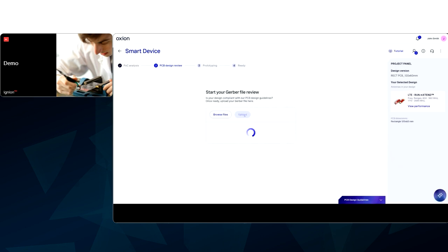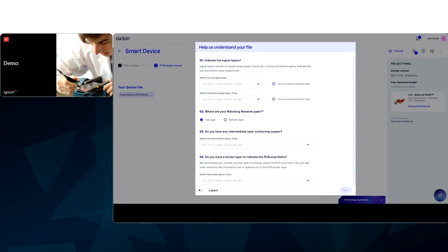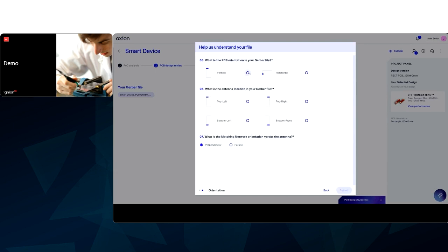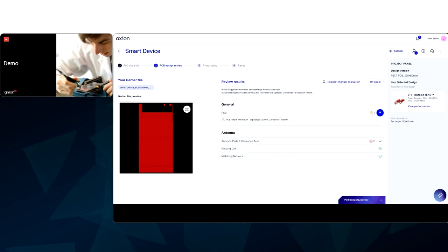All you need to do is upload your Gerber file onto the platform. As long as you're following the proper design rules, you've got design rule checks, pretty much like any of your PCB design software would, Altium or whatever you use, then everything should be okay. You can output your design and off you go to manufacture. But if not, you're going to get some errors. But yes, the platform does walk you through the various stages on how to do that.